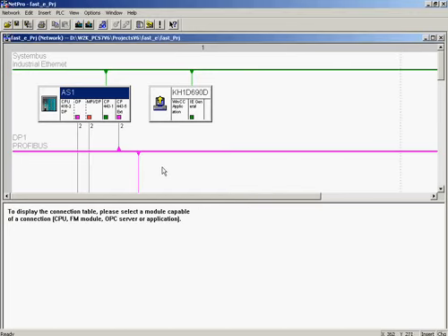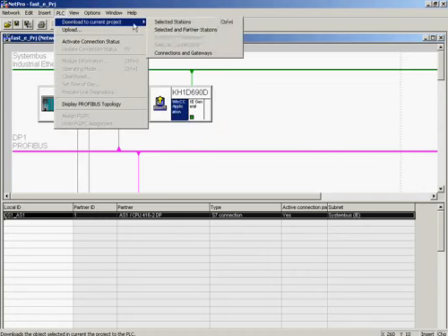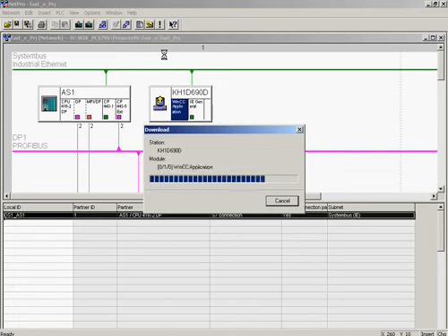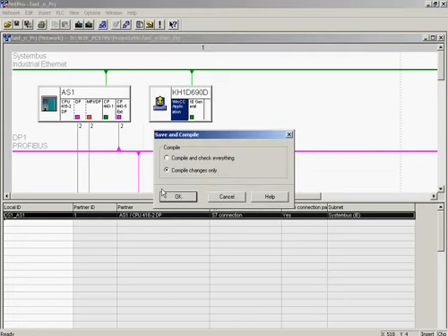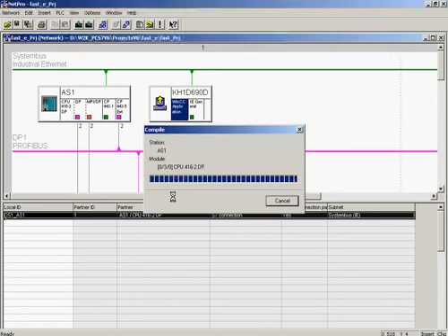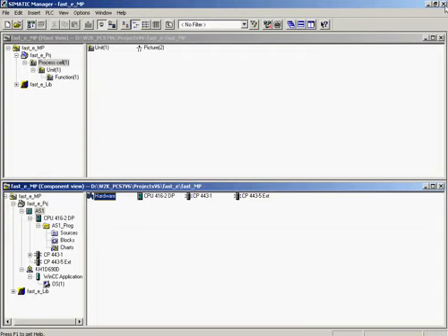In the last step, the named connection is loaded into the schematic station. The WinCC application is selected and the connection is loaded. NetPro and HWConfig are terminated. The hardware-specific part of the configuration example is now finished. You are now ready to begin configuration of the actual application program.